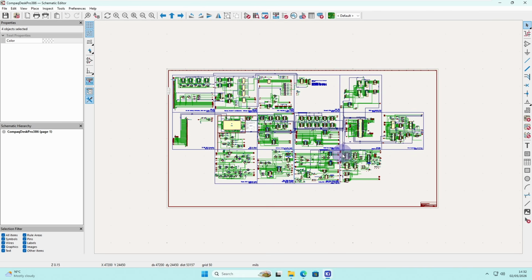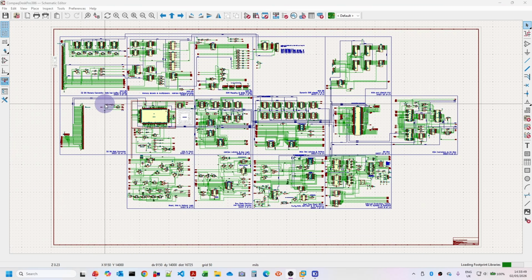What I'm going to do is to switch to my main PC now. We've got this installed and configured and open properly. There are just a few problems with the VM and the OBS software capturing the VM output. That means that it doesn't quite show all the lines and things. So that's how to go about downloading KiCad and actually loading the DeskPro 386 schematics that I've uploaded onto GitHub there. So in fact, this is now the KiCad running on my main PC rather than the VM. I just wanted to show how to install it on a clean environment.